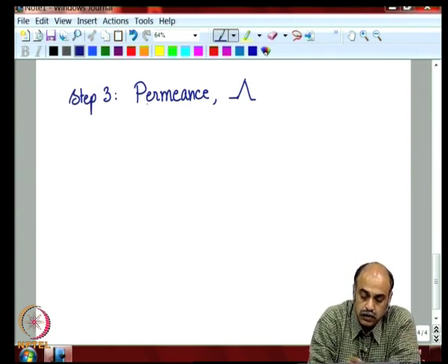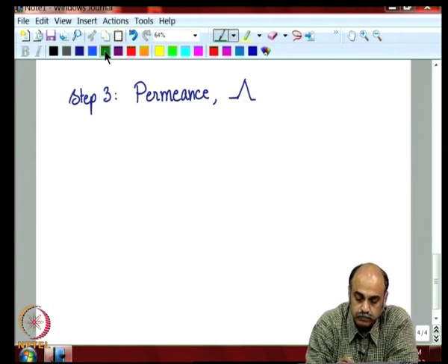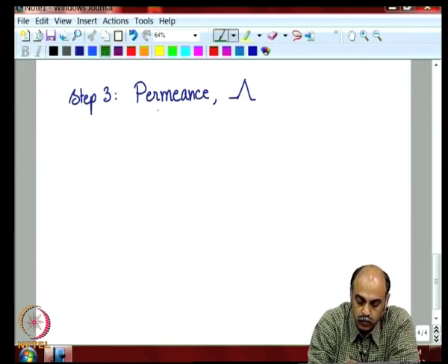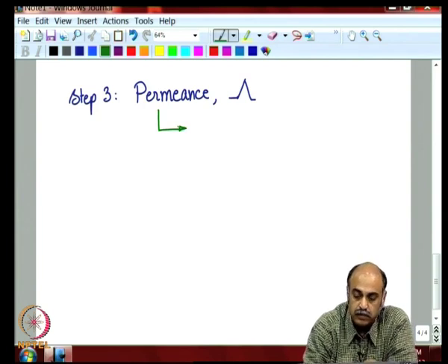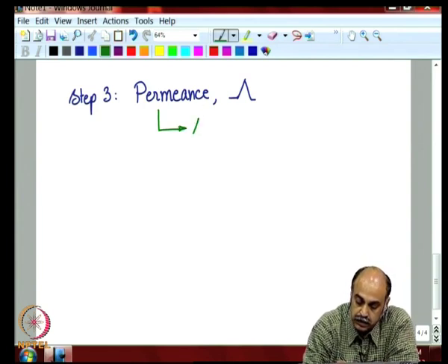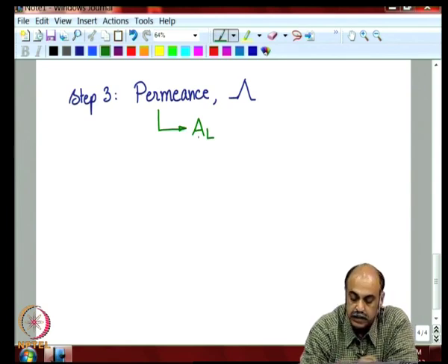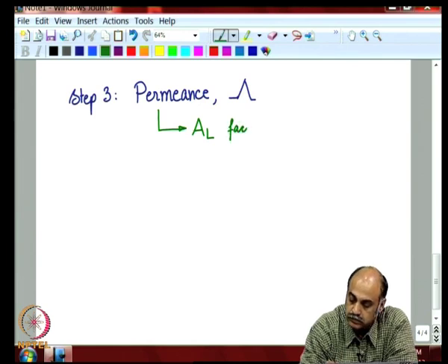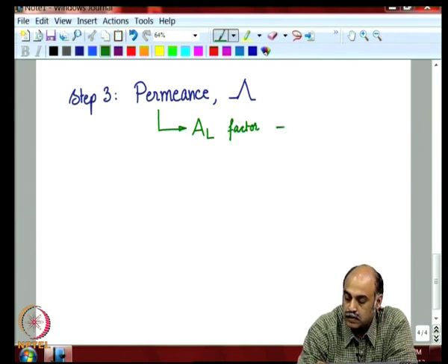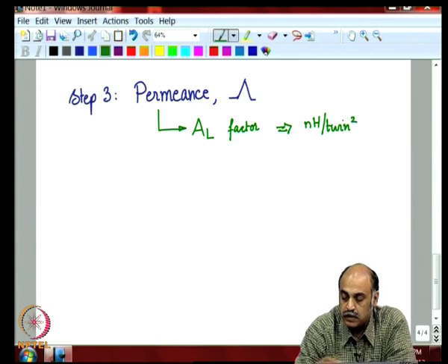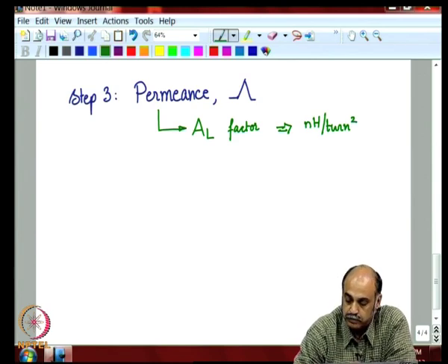and if the reluctance is higher, the permeance will be lower. So, if you are using a core where it is made specifically for inductor application, the manufacturer will give in their data sheet a factor called the AL factor, in nanohenry per turn square. This is nothing but the permeance expressed in nanohenry per turn square.